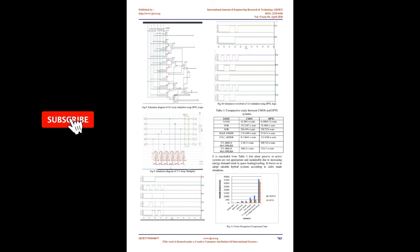In power applications, average power consumption is a critical design concern. Leakage current, which is primarily determined by the fabrication technology, consists of reverse bias current in parasitic diodes formed between source and drain diffusion and the bulk region in a MOS transistor, as well as the sub-threshold current that arises from the inversion charge that exists at gate voltages below the threshold voltage.